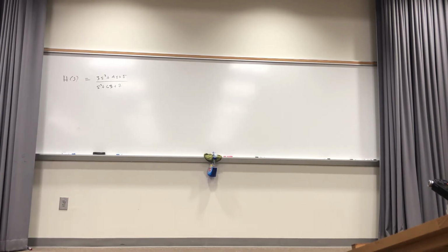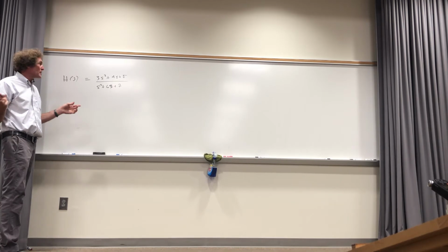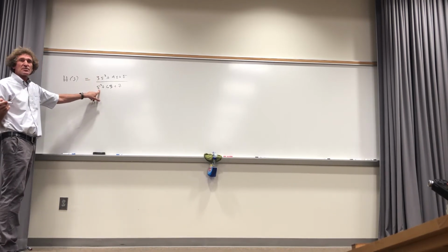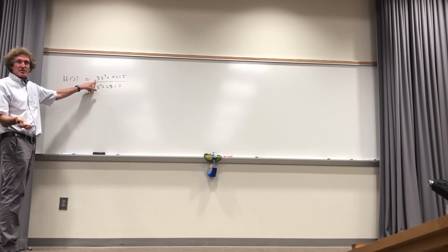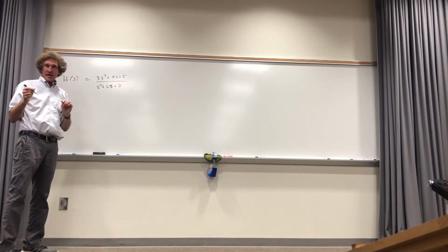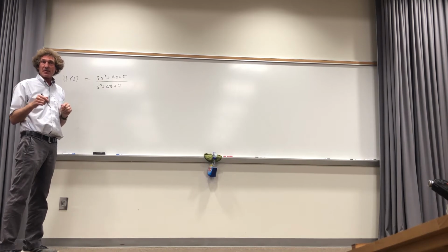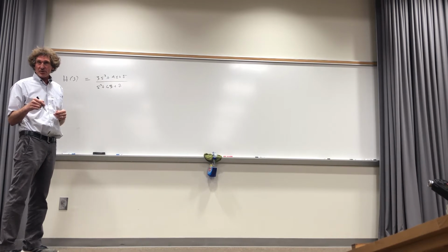If you want to see what it looked like, you could plot it. If you look at this in the limit at high frequencies, if you look at the power of s squared top and bottom, in the limit this thing will go to 3 at very high frequencies. It'll have a gain of 3. In the limit at low frequency, when you're at s equals 0, 5/7 is the gain. In the middle, you're not sure. It's got a couple of bumps, basically. Follow me on this, class? But this is nevertheless a transfer function that you have to realize a circuit that'll do.